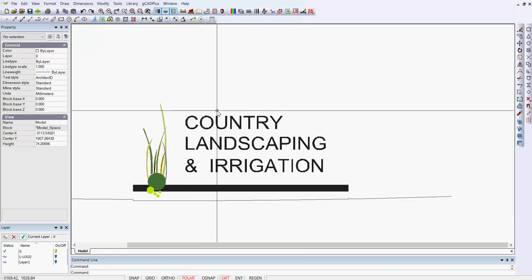So I hope that helps. Very shallow arcs like this and trimming off very small pieces like that can be just a little difficult, but remember, if you just vary your order of picking, the thing to remember is first select the cutting edge, then right click and select the object to be trimmed, trim it off and work that way.